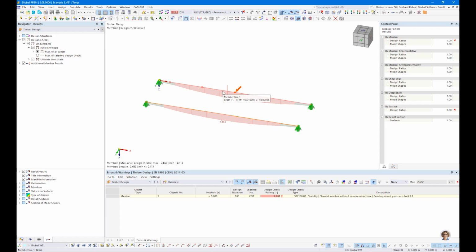It's not exactly factor 0.9, but in reality it should be factor 0.885, for example. And also adding 2 times the beam height is not perfectly correct. That's why we have a different approach. If you would use the German approach from the German annex, you would get a smaller buckling length, and then this one should be nearly the same.